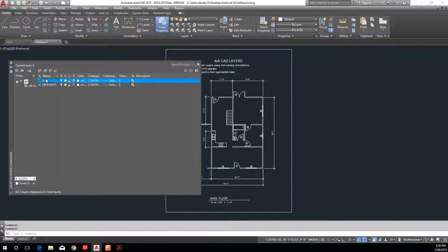Okay, they have a purpose in AutoCAD. The purpose of layer 0 is for creating blocks, which we don't know how to do yet. And def points, it's a non-printable layer that is used for dimensions, essentially. And so we're going to kind of leave those 2 things alone for now. But do know that they are in there, and so you will see them, okay?